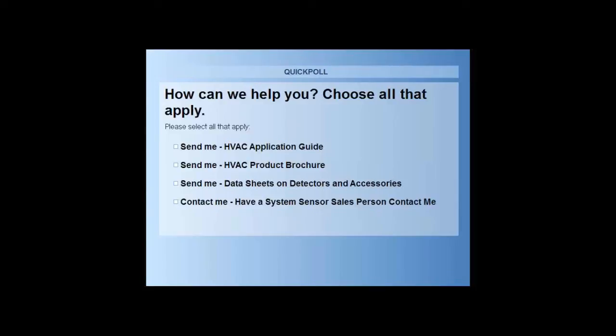Our number 4 question says, a frequent problem with smoke detection for air handling units is some don't actually have ductwork on the return side. How do you install a duct smoke detector housing on the return side in these situations? In these situations, we would recommend that the detector can be put on the supply side. If that is not acceptable to your AHJ, you could also use pendant mount smoke detectors that can be installed near return vents or in open area plenum return.